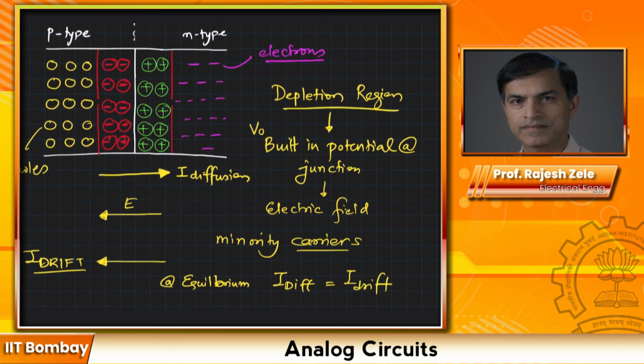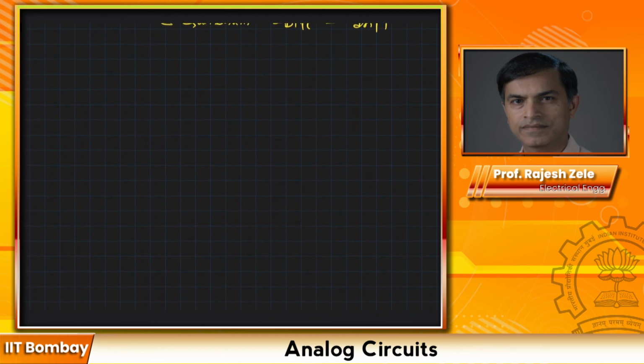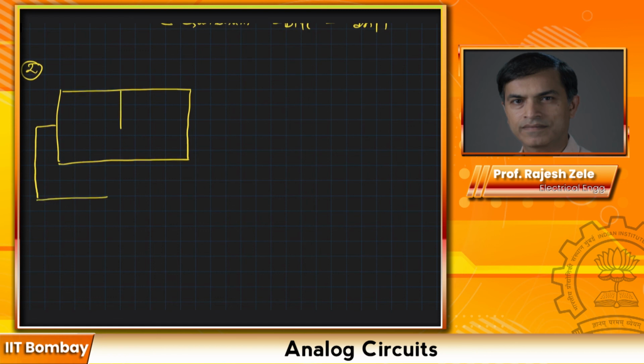Let's apply some external potential and see what happens. The first case was open circuit. In this second case, we take a semiconductor, this is P and this is N, and I am going to apply a battery potential here, negative potential on the P side and positive potential on the N side. This is the negative terminal of the battery, this is the positive terminal. Let's call this VR. Since we are applying negative potential to the p-type material, we call this reverse bias.